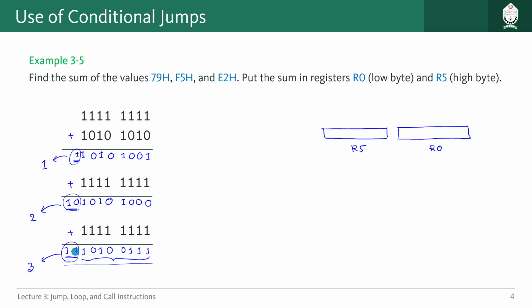So we are going to do the arithmetic on register A, obviously, and each time there is a carry, we are going to increment the value of R5 starting from 0. So 0 to 1 to 2 to 3. In this way, the upper bytes will be saved on R5 and lower bytes will be saved on register A.